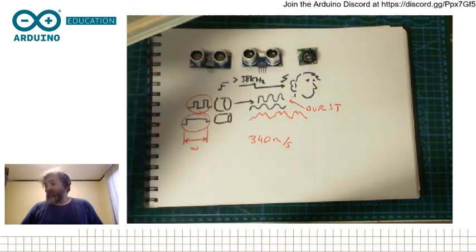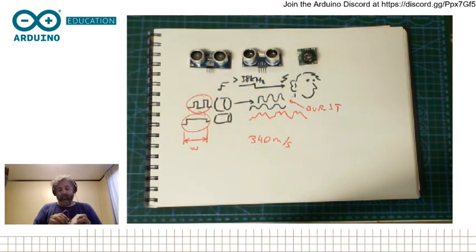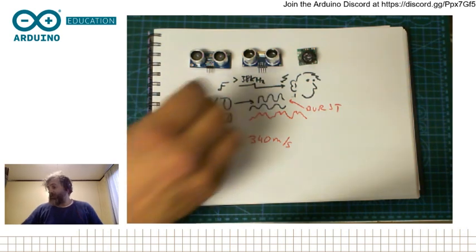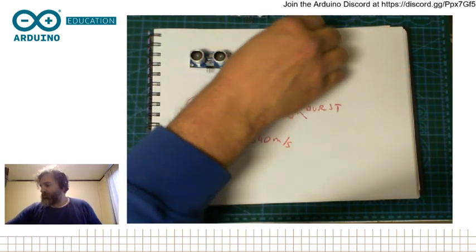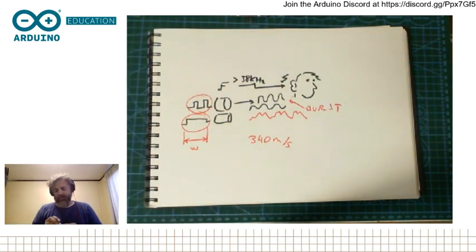So the way you connect this again goes through taking your board. I will dismount the previous circuit that was pretty simple to build, and I'm going to start using the ping sensor because it has 3 pins. What happens with the ping sensor is that it has a 0 volts pin, a 5 volts pin, and a signal pin.